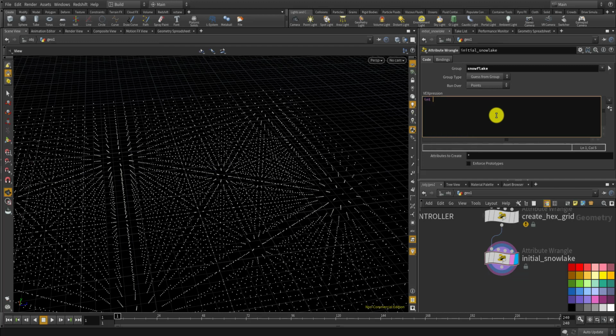First of all, let's get the new points from this snowflake center point using the near points, looking at the position P. Since the distance between points is equal to 1, if you want 20 cells, you need to look at around 2 cells, so look at a distance of 2. But since this is a mesh-based calculation system, the 2 might not catch every point, so I'll add some offset value like this. Okay, and for each int npt in near points,